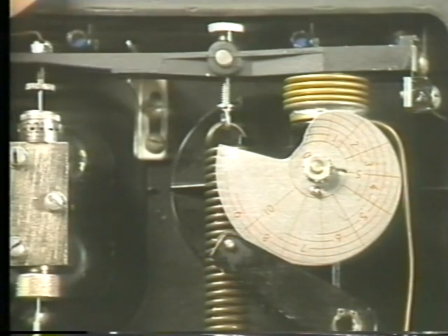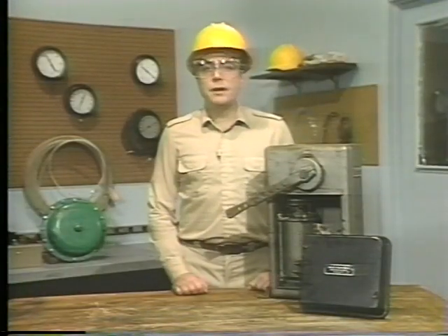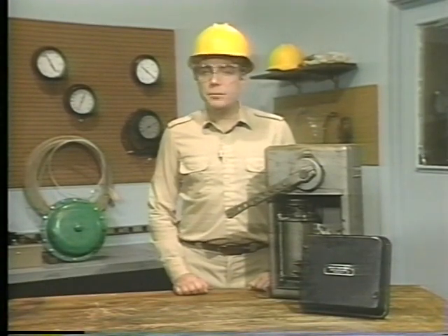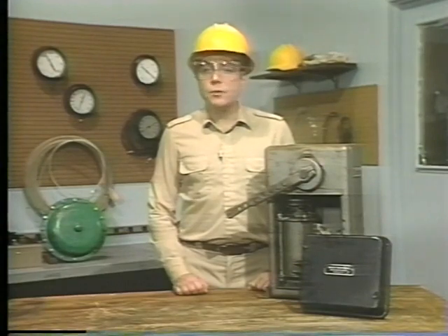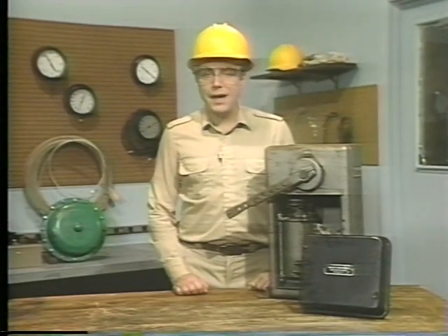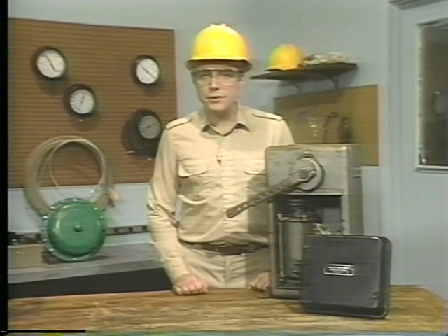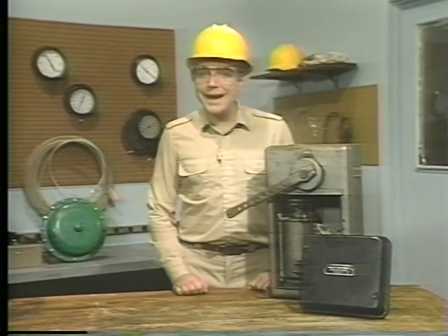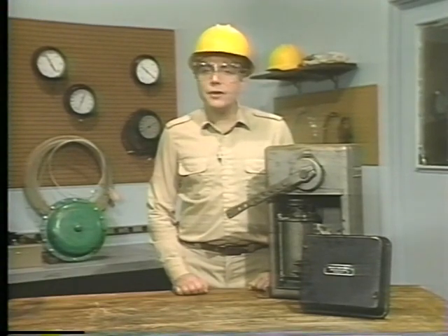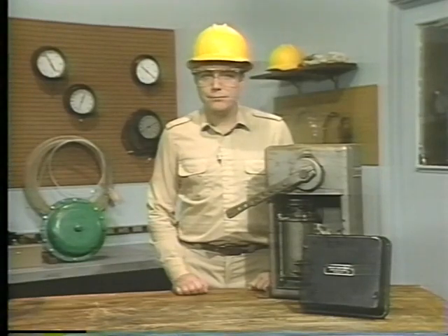After performing all of the checks and adjustments that we just saw, the procedures should be repeated to be sure that all of the adjustments were correct and the instruments are working properly. Then the manual loader can be disconnected, carefully following the safety procedures used when the instrument was connected. Finally, the positioner can be reconnected to the control air supply and all the covers remounted.